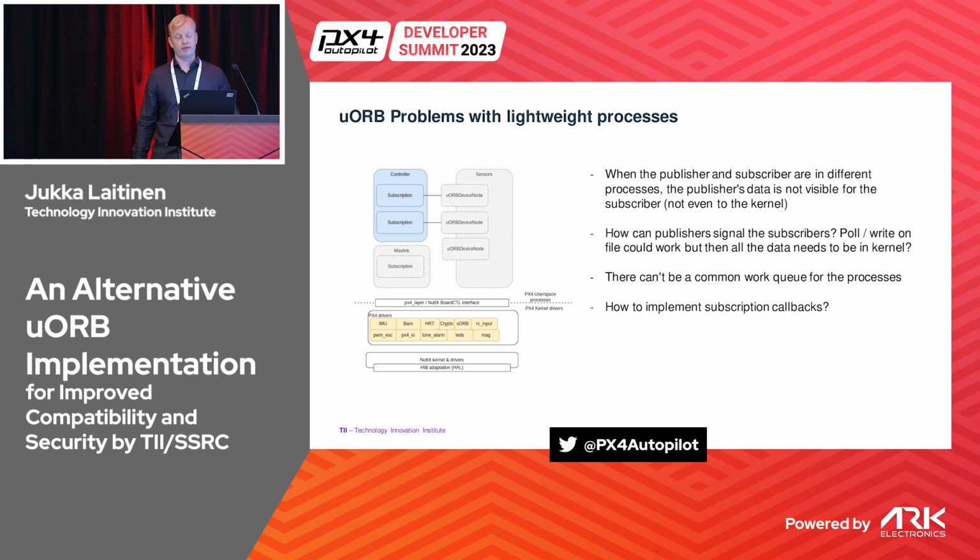If you have two processes, or two PX4 modules, one which I call sensors and another which I call controller, they are imaginary processes, but actually there is a module called sensors in PX4. Now the sensors process is producing and publishing data in those uORB device nodes, which have memory allocated in the context of the sensors process's own memory space.